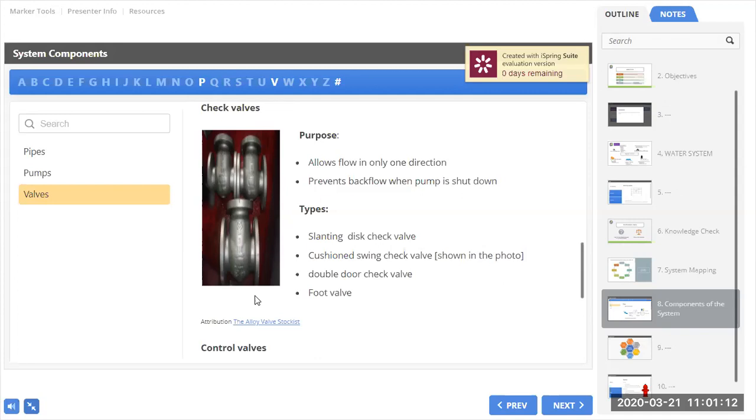The second one is to provide water for peak periods and emergencies. So that's where we look at storage. Firefighting storage as well, and pressure. But it is also there for peak periods, because peak periods are periods where we have most of our consumers using the water system. So they are using water. Now, peak periods, usually this happens if you're in an industrial zone, then you'll have a peak period in business hours where things are being used.